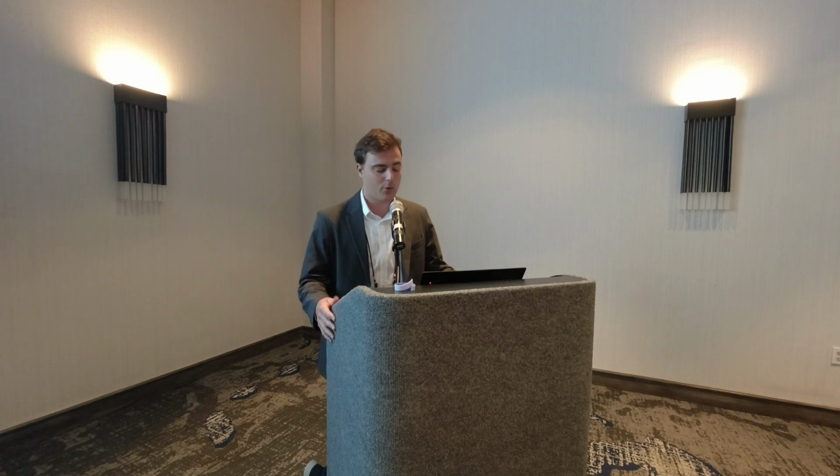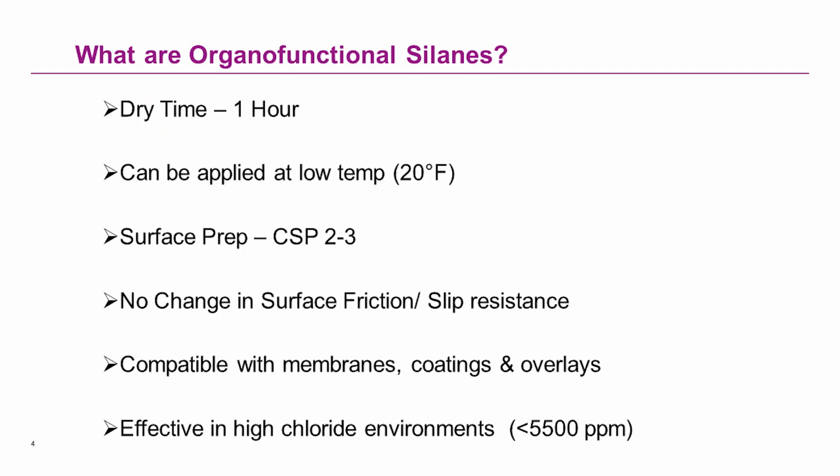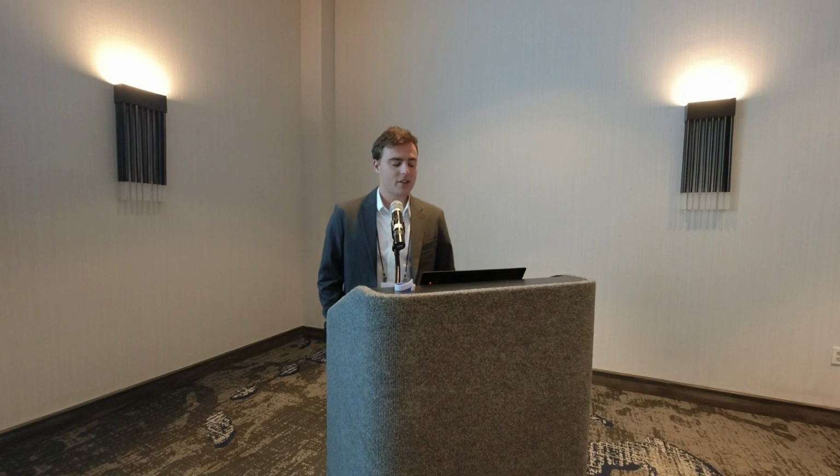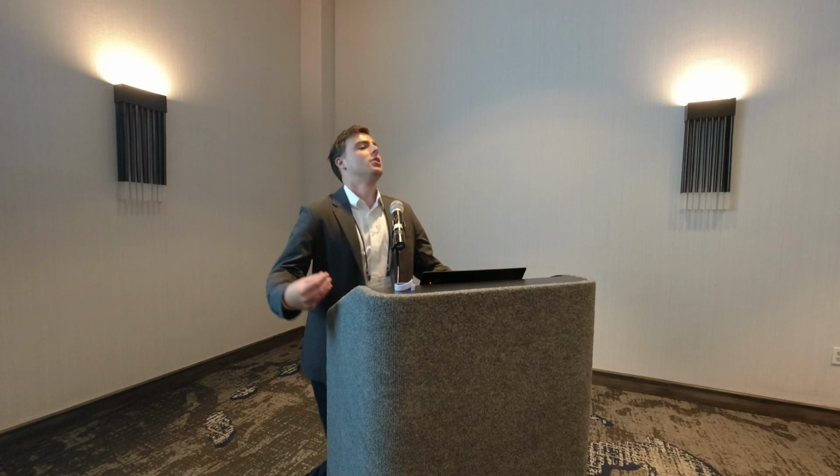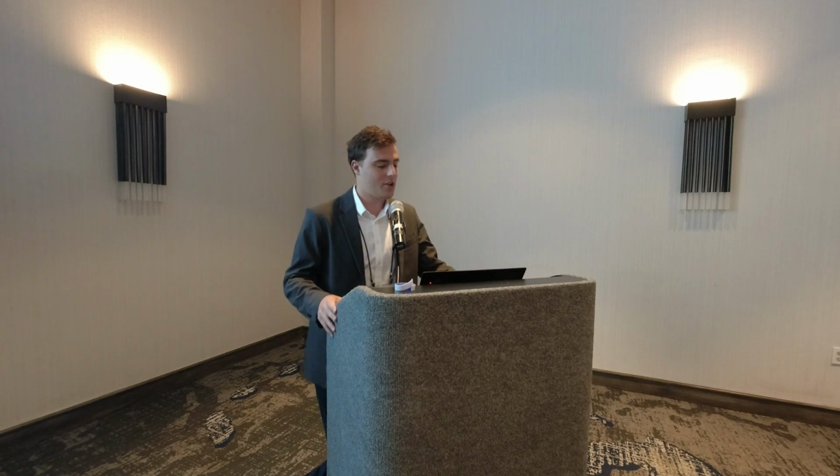Organofunctional silanes, just like your normal water repellent counterparts, don't change the surface friction, they don't change the slip resistance once they're dry. It's important to say once they're dry, you shouldn't open the bridge deck until it's dry. And then once they're on, they're compatible with membranes, coatings, and overlays. They are hydrophobic, so if you're using a water-based membrane on top of them, the application may be different. You may get some resistance, but the act of brushing, using a roller, or even spraying on a coating will break the surface tension, which will allow the coating to stick to the concrete, and the surfactants inside of these coatings, membranes, and overlays are never an issue. And then finally, organofunctional silanes are effective in high chloride environments.